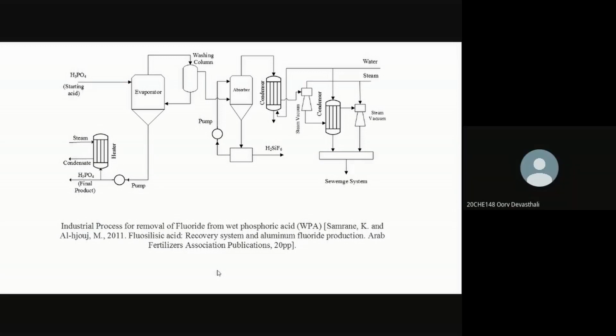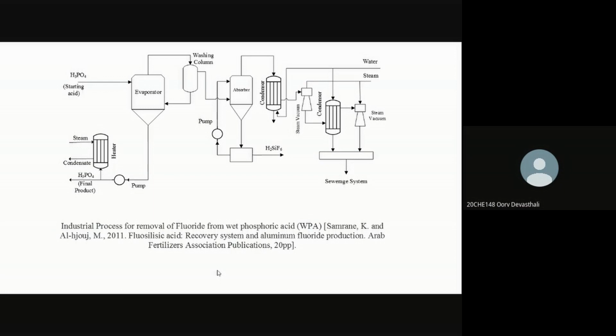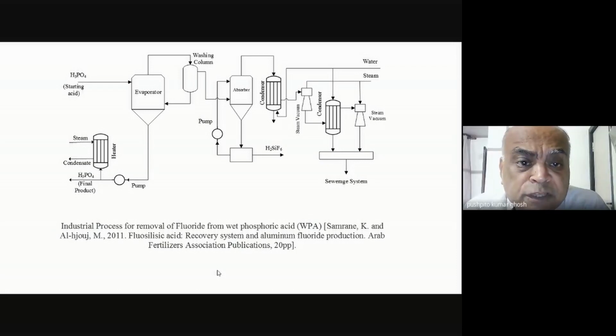But I have a small doubt. Yesterday while giving the reaction, you said that calcium phosphate with sulfuric acid will give gypsum, like CaSO4 in the form of 2 H2O. But then why not convert this into the hemihydrate, like adjust the temperature such that hemihydrate is formed? No, no, this is downstream. This is after you have made phosphoric acid. You're starting with phosphoric acid.